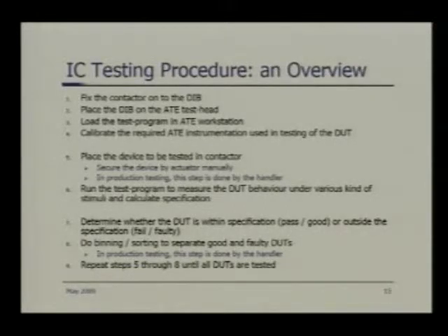Then you run the tests. You are applying a series of test stimulus, capturing the waveform, and using the test stimulus waveform and the test response capture waveform, taking them together, you're calculating the test specification, for example, gain, output by input. You do it over multiple frequencies.